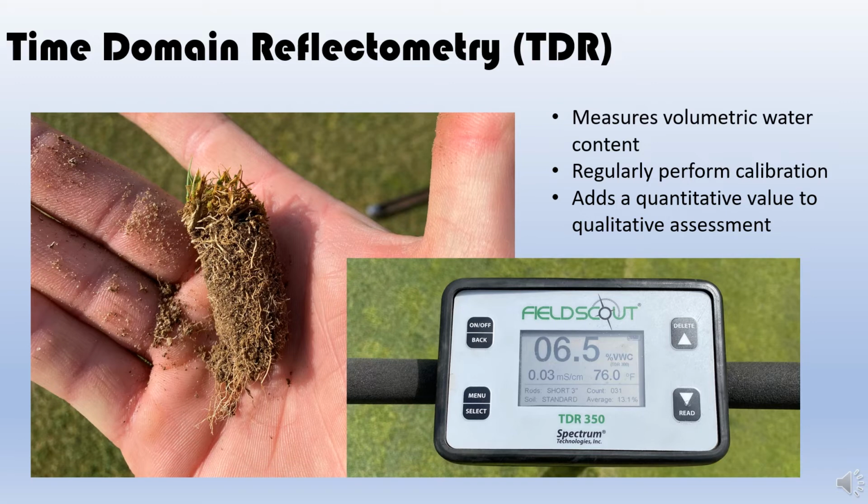You calibrate the probe by taking a soil core and a meter reading from the same spot. You assess the moisture level of the core and record the meter reading. The variable soil textures on Laurel Creek's property require that your qualitative assessments give meaning to the quantitative reading from the meter. So the meter reading should be relative to your assessment of the soil moisture.